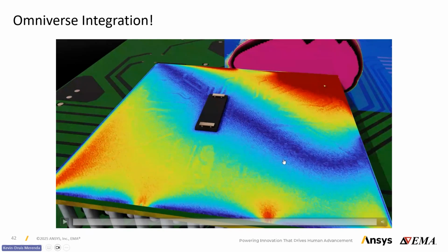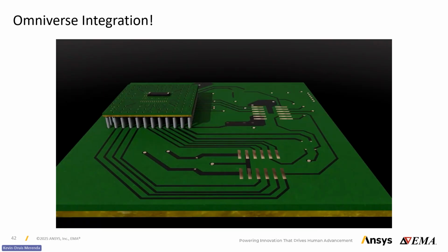Ultimately, you want to understand how each of the components on the board are responding to this discharge that is happening at the chip level. And if you can change the properties of one of those components to be able to understand if the current of the ESD changes, or if you're able to limit current flow down the line due to a diode that you placed in the system, like a TVS, for example.